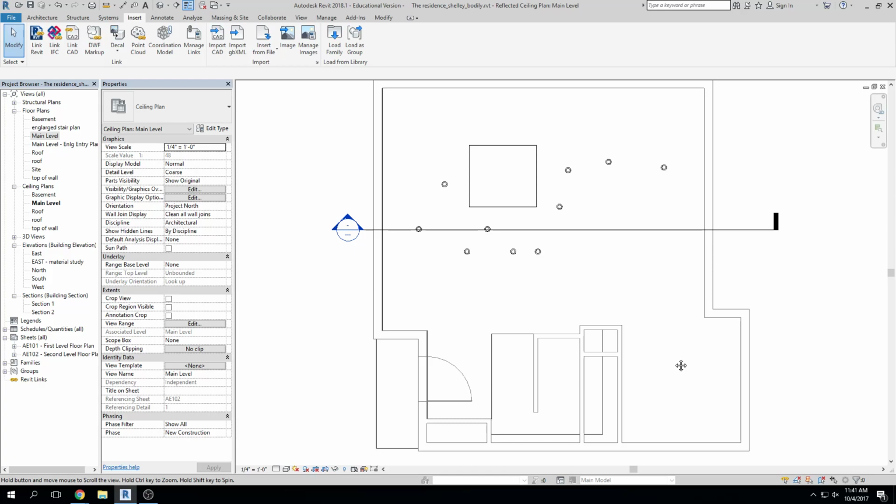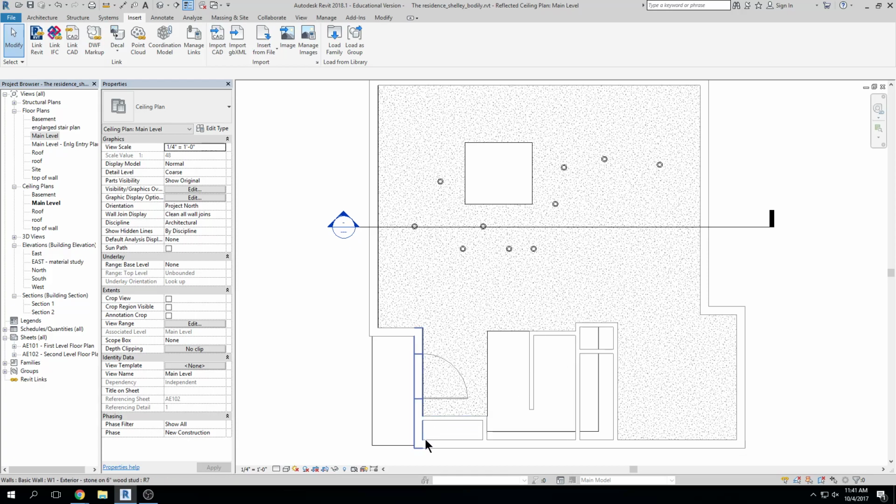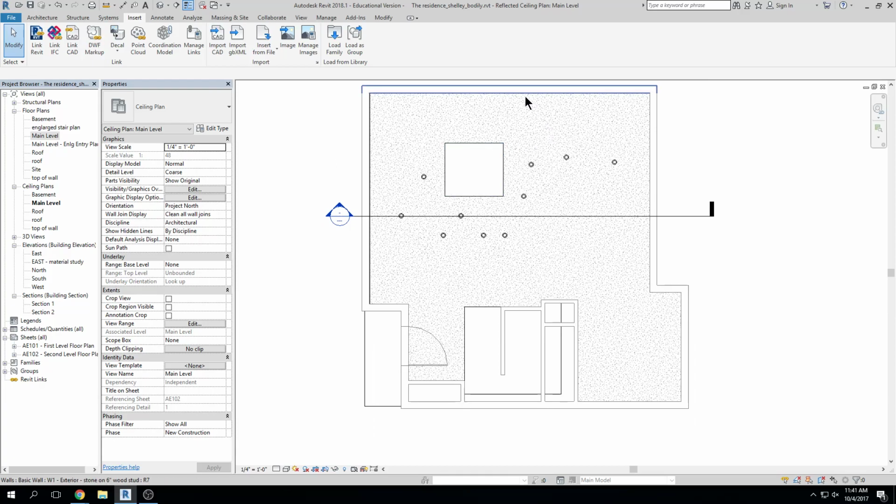Before I do that, one quick note, I haven't done this little ceiling in this closet, which you normally would. I guess this is a little bit of a workflow question as well. Some places like to do the ceiling all as one piece, right? So you have a giant floor of a building and they like to do the ceiling all in one piece. I found that maybe a better way of doing your ceilings is in small chunks, so that if you have to change something or delete something or alter the level of some portion of the ceiling, you can do that easily without deleting everything.